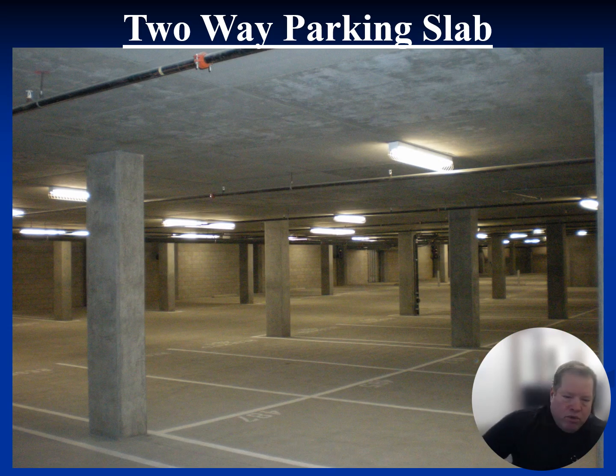This is a typical view of a parking structure. Hopefully you can see the columns right here. Relatively small, considering that it could be holding up 5 or 6 stories of concrete. Not a whole lot of moment transfer. Again, primarily axial load. You can see here, this is roughly about a 29-foot span in this direction, and that's roughly probably about 28 feet in that direction. So the slab thickness is based upon, obviously the greater of the two, but they're basically the same value.